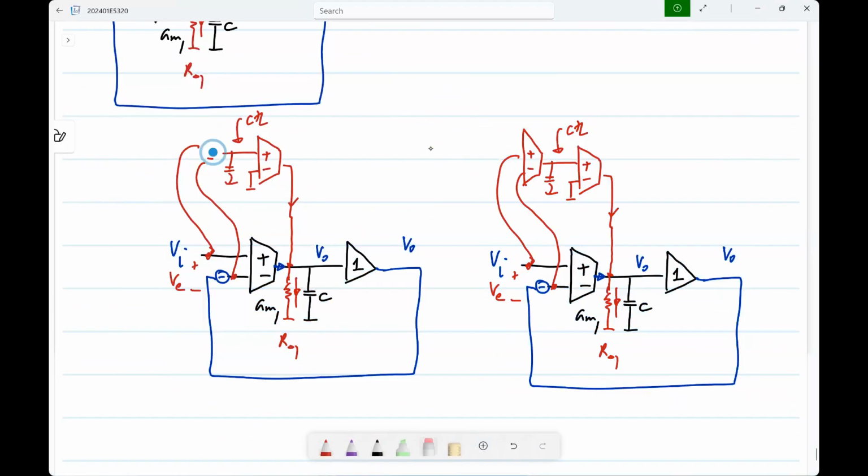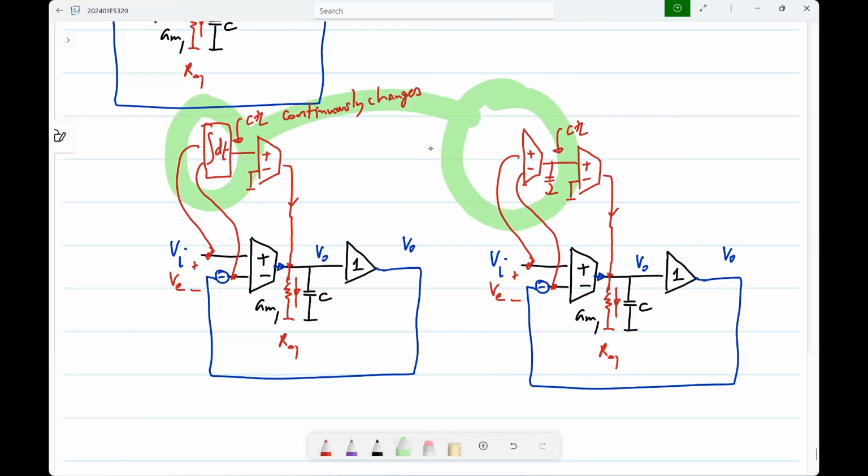So what we wanted here was an integrator so that this control continuously changes based on the error we see. Now, of course, how do you make this integrator? We had our single stage op amp. Let's say that's the only op amp we knew. So we replaced that with the single stage op amp. That's what we did. This other GM is for just making a variable current source.